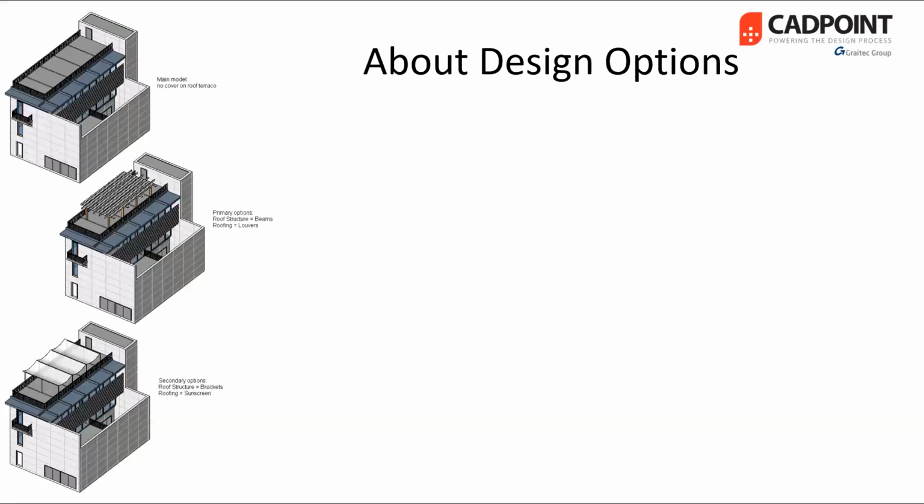With design options, a team can develop, evaluate, and redesign building components and rooms within a single project file. Some team members can work on specific options, such as variations of a lobby, while the rest of the team continues with the main model. Design options can vary in complexity. For example, a designer may want to explore alternatives for entry designs or structural systems for a roof. Design options tend to become more focused and simplified as the project progresses.